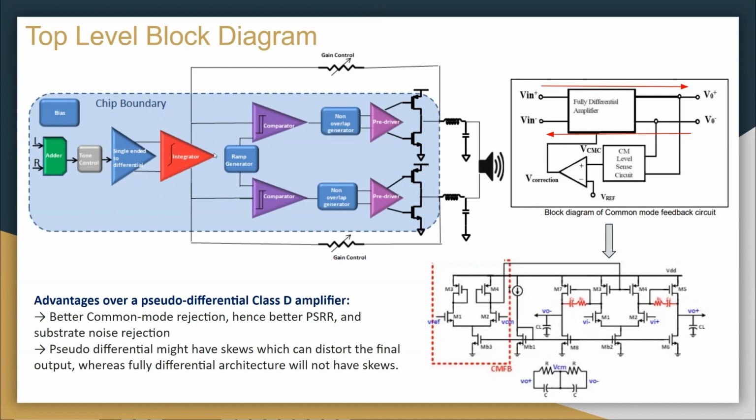is basically a ramp signal. So the output of these comparators are PWM signals. These generated differential PWM signals are then fed to non-overlap generators. What a non-overlap generator does is ensure that there is no shoot through current in the final output stage by ensuring the PFET and NFET never turn on together. This helps in not losing out on efficiency due to shoot through currents, and also prevents our final FET from turning on at the same time.